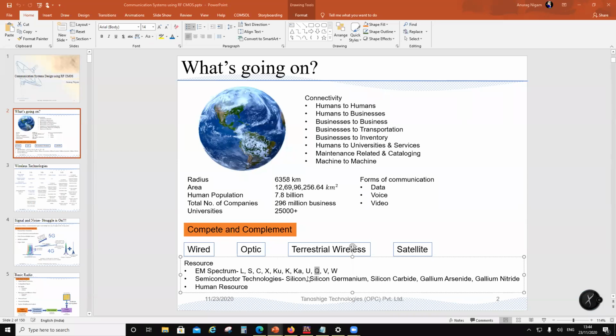And then there is going to be another high speed 5G around Ka band, which will be like 24.85 to 28.35. Again, it depends on country to country. For example, we have one big band for 5G in India, while in America you have 27.5 to 28.35, that band. So it depends on where you are designing for.